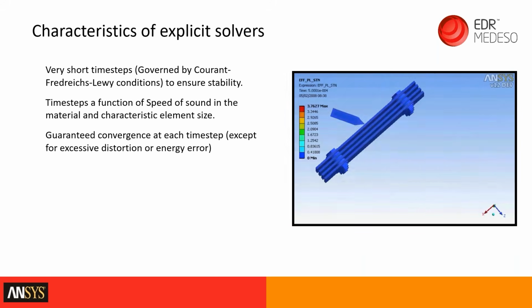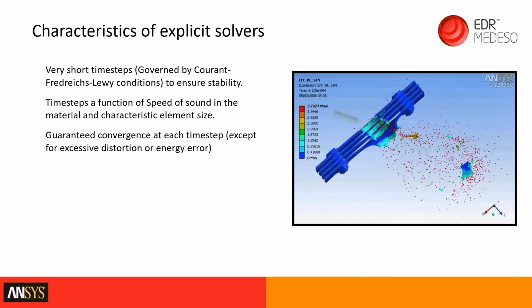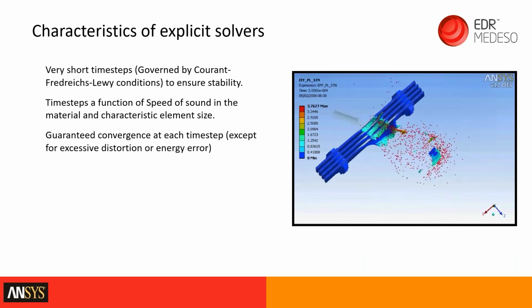So the time step is governed by what's called the Courant-Friedrichs-Lewy condition, and this is a function of the element size and the speed of sound in the structure. The time steps tend to be quite small, especially if you're using a high number of elements.